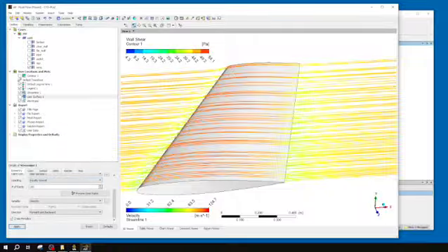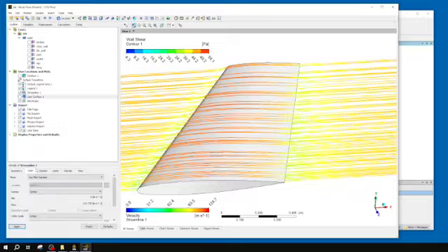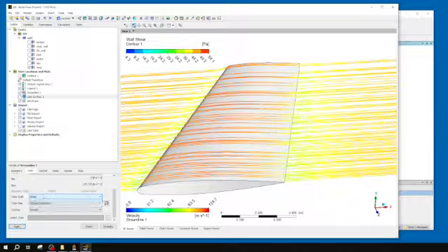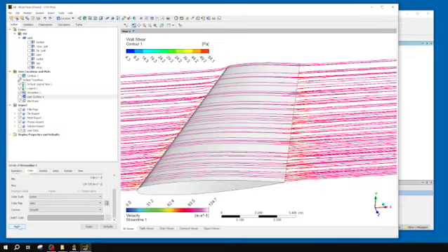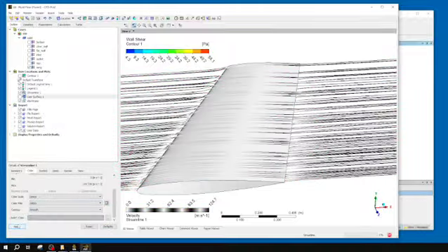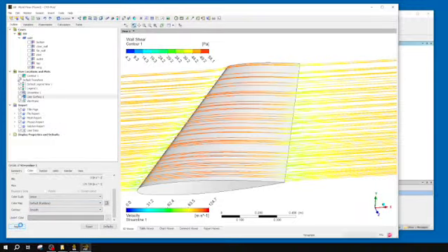Couple options I want to point out on this one. First, this color option, again, you can move it down to local or whatnot, change it to a logarithmic, change the color map, right? I don't necessarily know exactly what error looks like, but you can see that map down on our legend below. So you have kind of a bunch of different options. You can go a zebra, which is just going to be, I believe, black and white for zebra. Yeah, black and white. But yeah, I generally find the default makes the most sense, except for kind of niche cases. And again, I suggest keeping this one smooth.